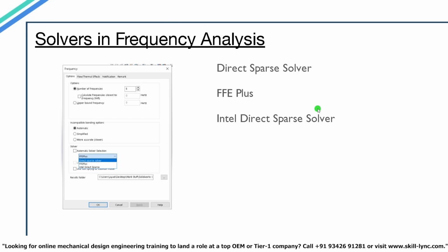When the moduli of elasticity of the materials used in the model are very different, let's say in the same model you have 2 different materials, for example steel and nylon, then iterative methods could be less accurate than direct methods. In such scenarios, direct solvers are recommended. When performing analysis where there are no interpenetration contacts and bonded contacts, direct solvers tend to solve these much faster. So with this, let's move on to the software part.